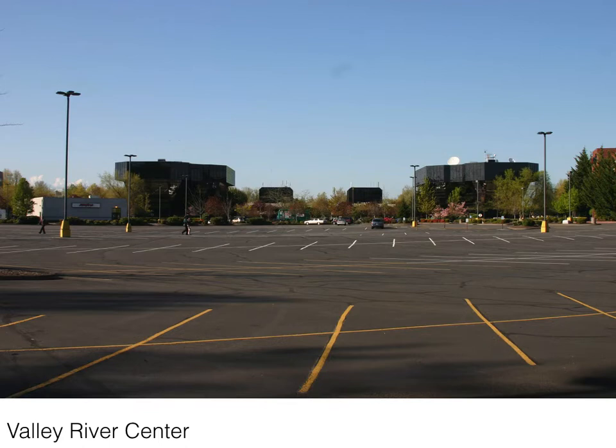Well, cars, the general assumption is a lane that a car drives in has to be 12 feet wide. You'll probably notice from driving, most people find it really hard to drive in a straight line and are constantly weaving back and forth in their lane. The slope on something you're driving, you've got about a 10% maximum slope on driveways. Highways, 6%, as I mentioned, is considered quite steep.